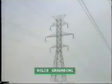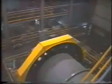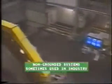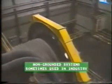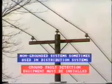Now at this point, let's briefly summarize the methods of grounding which you will encounter. Solid grounding. This is the case with most utility systems above 40 kV. Generators may be grounded through an impedance so as to limit the magnitude of fault current. Non-grounded systems are sometimes used in industry where a continuous power supply is required. Distribution systems are sometimes not grounded, and in this case, ground fault detection equipment must be installed.